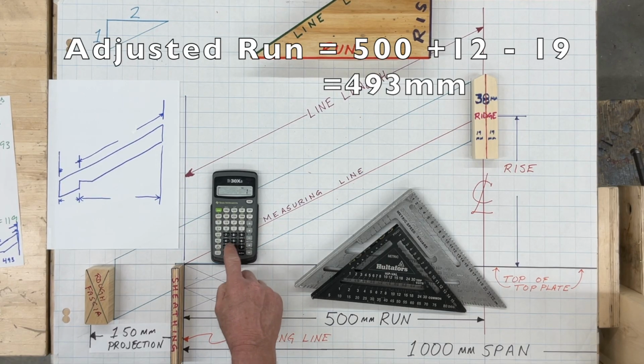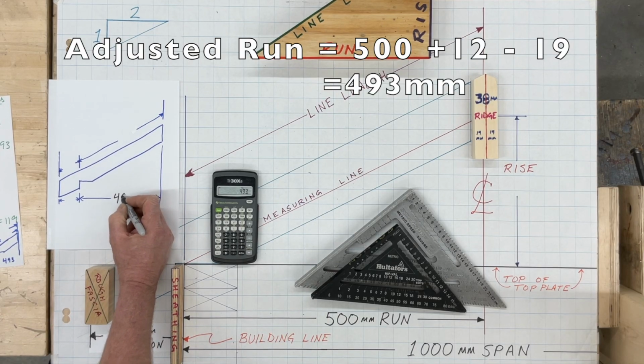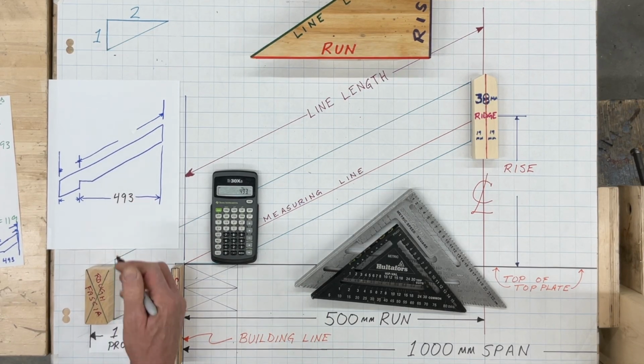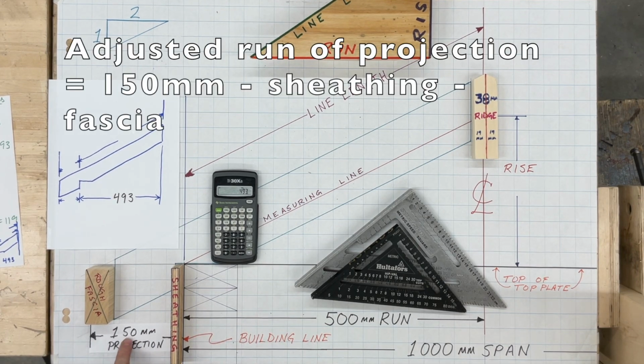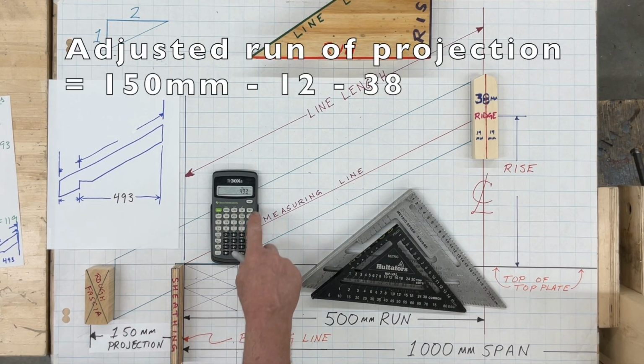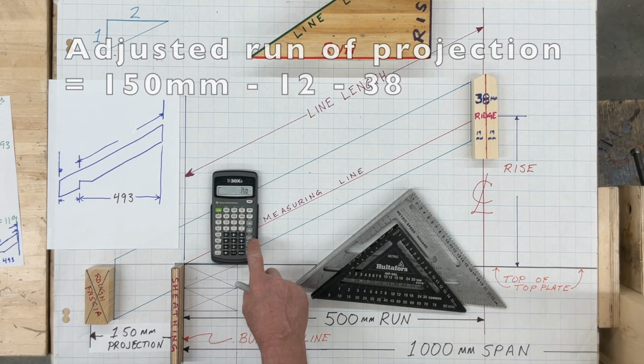This leaves a run of 493 millimeters between the ridge plumb cut and the bird's mouth plumb cut. From the 150 millimeter run of the projection, we need to subtract the thickness of the sheathing and the 38 millimeter thickness of the rough fascia to get the adjusted run between the bird's mouth plumb cut and the tail plumb cut.